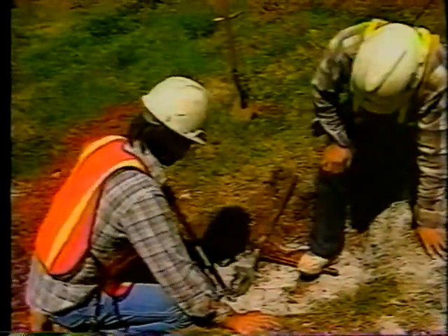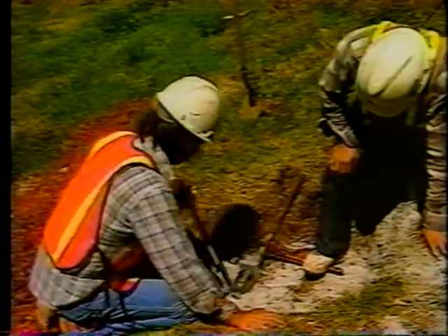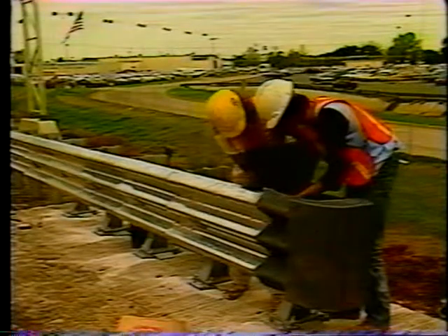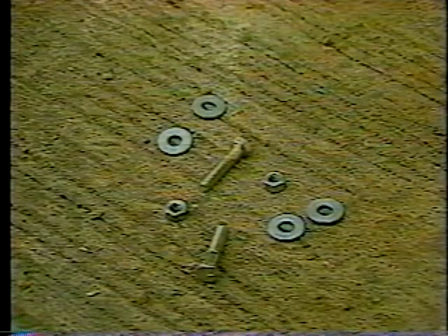The nut threads need to be fully engaged to the threaded cable ends. Next comes sandbox placement. The sand containers are attached to posts 1, 2, and 3 and are labeled with their proper post numbers. Place the correct container on each side of these first 3 posts. Use 2 bolts, 4 washers, and 2 nuts to attach the containers, sandwiching the post and blockout between the containers.